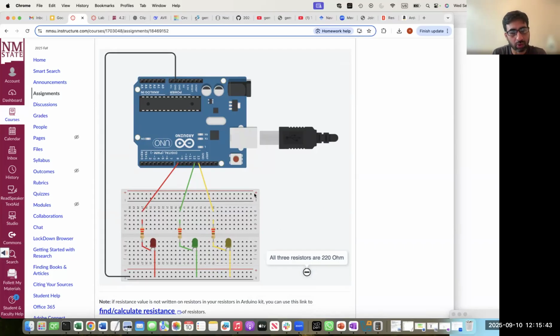First, you see plus and minus signs on the top and also on the bottom. All of these lines, like this first horizontal row, are shorted together, which basically means that if you provide the high voltage at this point, you will get the same high voltage at this other point. Normally you connect the high voltage in this first location. The next location, which shows a minus sign, is for the low voltage or the ground, and all of these dots are connected together. So if you provide the ground voltage here, the same ground voltage will become available here as well. The same goes for the plus and minus signs at the bottom.